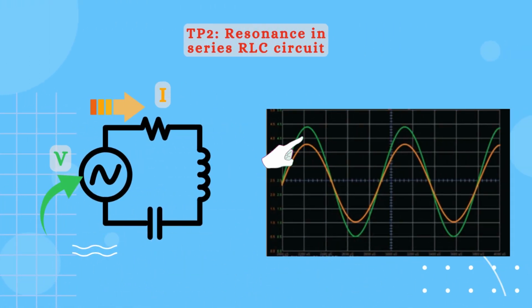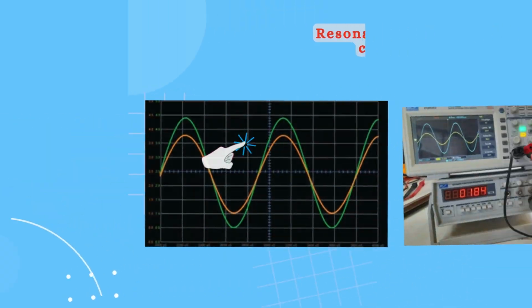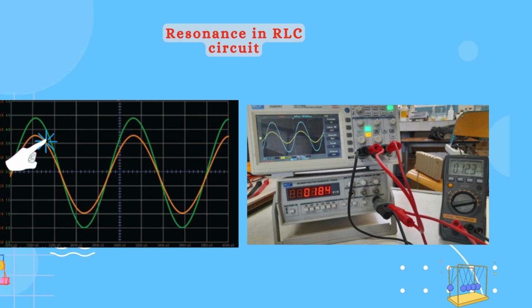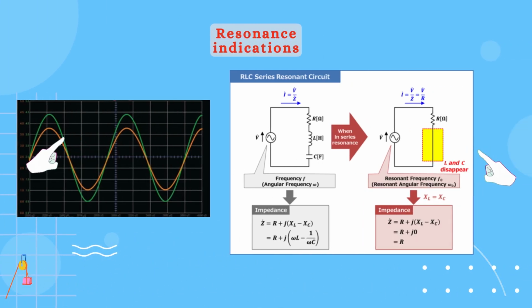Simply, resonance. What's resonance? This phenomenon occurs when the circuit natural frequency matches the frequency of the applied AC voltage, like it's shown in the figure. How to get it? We'll vary the frequency of the AC supply, and by using the oscilloscope we observe the current in the circuit. At resonance, the resistor voltage and the current through it become in phase. This is like there is no inductance, no capacitor. Actually, it acts like it's purely resistive, like it appears in the figure.